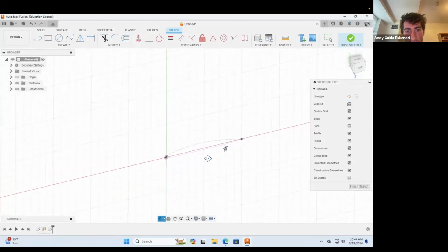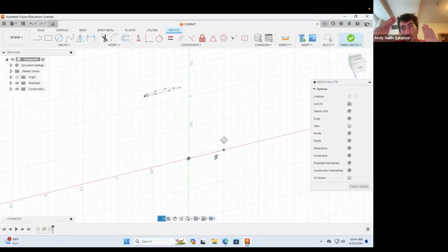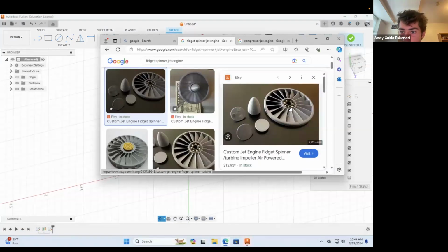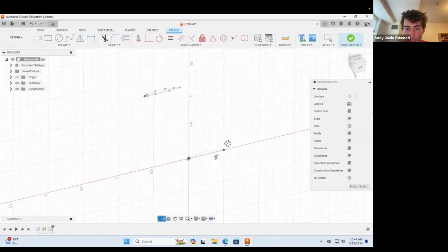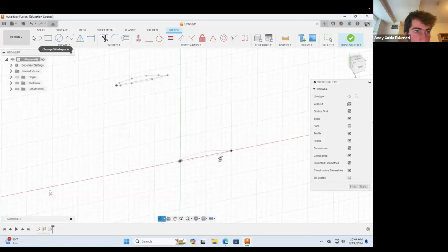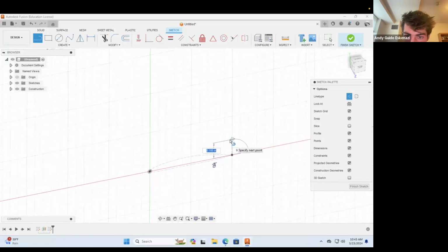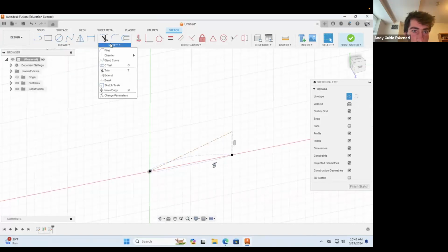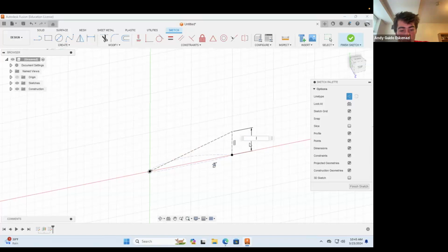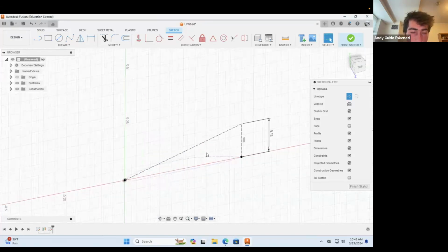But now I'm gonna make a slightly different blade design that's gonna be twisted by a little bit. And you'll see what I mean in a second, right? Because there's an angle there and there's a slightly different angle there. So I'm gonna give it some twist. In essence, what I'll do is I'm gonna draw a construction line that's gonna go maybe like that. So there's gonna be a lot of twist as you can see. And then as usual, we can say, where's our friend the dimension? We can dimension that. Yeah, 0.15. We can make it however we want.